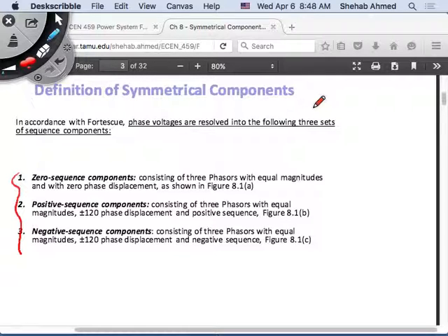It will tell us, you will look at numbers, you will look at the positive sequence, negative sequence, and zero sequence values, and you will know that, okay, there's a cable connected to ground somewhere. You will know by looking at the numbers. You will know that there's an unbalance, but the system, this unbalance is caused by two phases touching each other. You will know that by understanding what symmetrical components theory provides. Right? So that's the objective of this symmetrical components theory chapter.